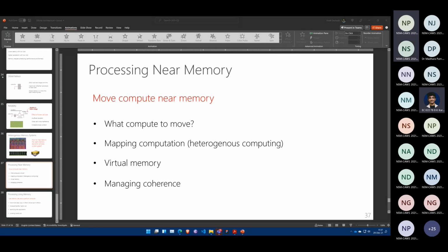When a load is followed by a store operation to the same location, can this be exploited by the microprocessor to save recharge time? Actually, like I said before, whether you do a load or a store, you restore the data, so it doesn't matter. In fact, if I just read from a particular row, I am actually refreshing the data of all the cells in that row, correct? Because the restoration process will essentially take it to the extreme, fully charged or fully empty, which means we can actually avoid refresh to a row which has recently been, quote unquote, activated.